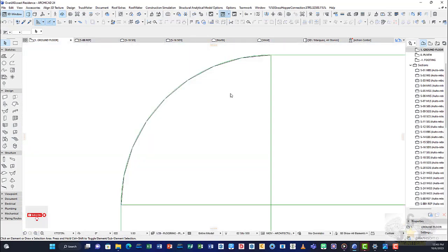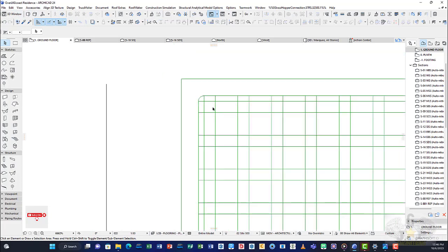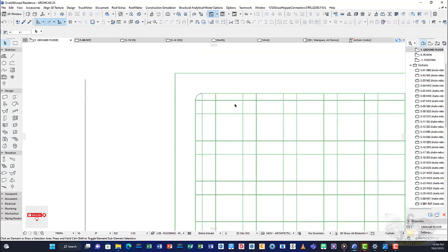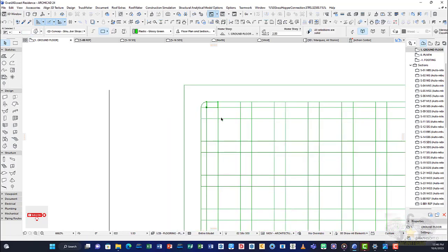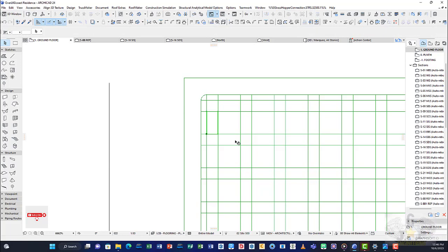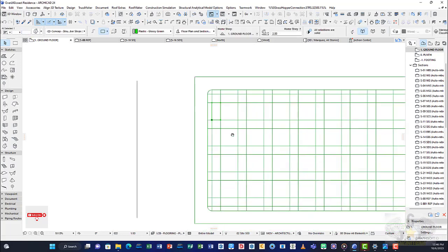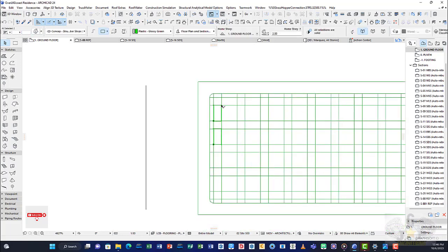We just want to do the copy and drag, right? So let's do it now. Let's play with the copy and drag. We're going to zoom out. Remember, the horizontal elements, we're done with them. We are on the vertical elements. Okay, I'm going to click here. Before clicking there, I'm going to do something. I'm going to click on these two first, this one and this one. I'm going to click on one side, press the control button once to create a copy. The cross appears. Then I click here.